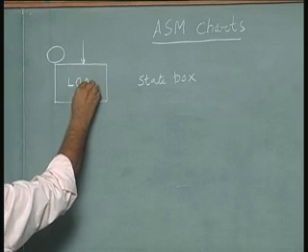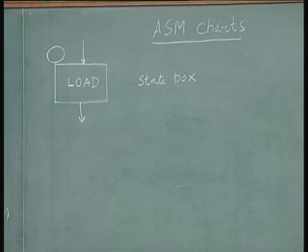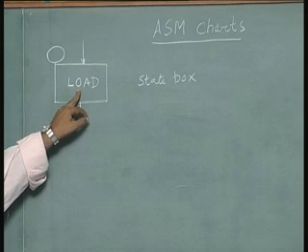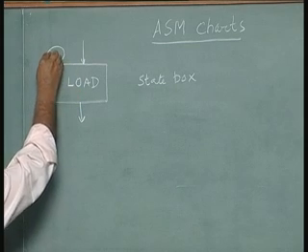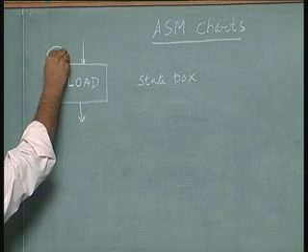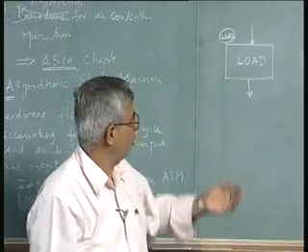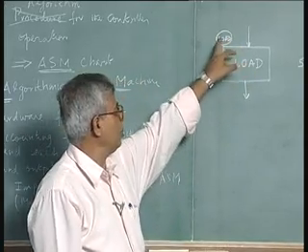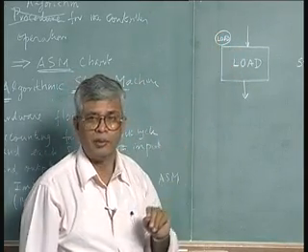Load may be a command signal I give to a register to load the input into the register. That signal will be issued in this state period, and so we will call this state the loading state. It does not have to be the same; it can be S0, S1, S2, or ABC, it can be anything, but usually you write something which can be easily understood. What is happening in the state will usually be understood by looking at the name of the state.